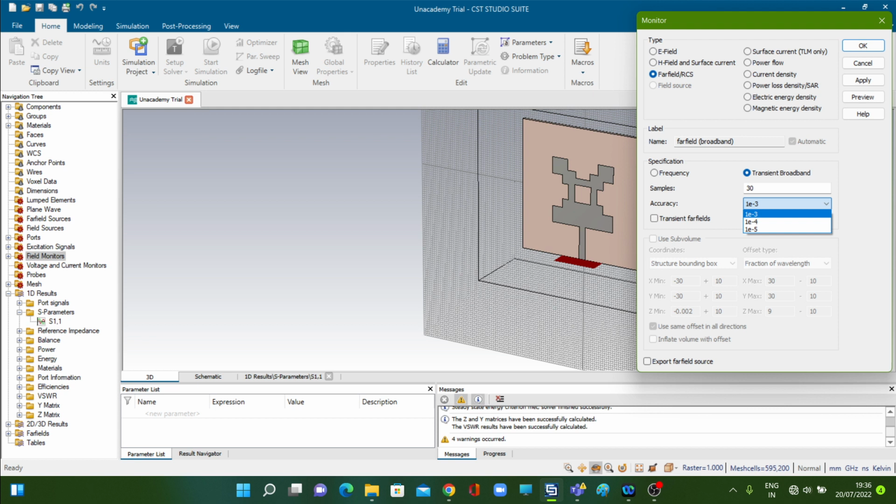structure at a very large frequency. But here we are not doing that. We have defined the frequency from 1 to 10 or 8, whatever, gigahertz. So for observing this difference, we need to select a much higher frequency. If you don't do that, level 3, level 4, level 5 will give you almost a similar kind of result. So if we are getting a similar result from the 3 levels, it is advisable to select level 3 only, because that will save me the computation time at least. Okay, so for this reason, we are selecting level 3.